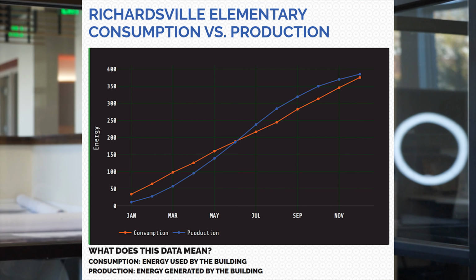So what makes the PV work a lot of the time is the lower ROI, the return on investment. Most PV systems have a return on investment of 15 to 20 years if you're a school system. This may be better or may be worse, just depending on the specific utility rate.